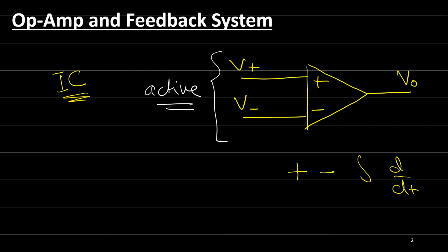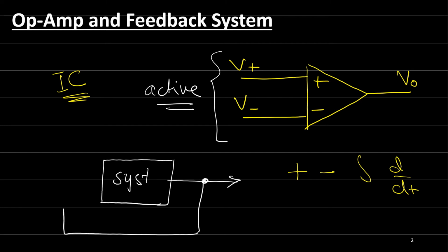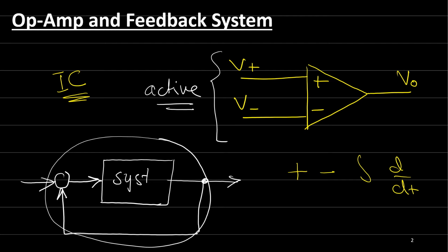One of the best solutions is to build an amplifier that has much more gain than the application requires. Then some of the output signal is fed back to the input in such a way that the overall gain depends on the feedback circuit. So if we take part of the output signal and feed it back to the input, the total gain of this feedback system can depend on the feedback circuit.